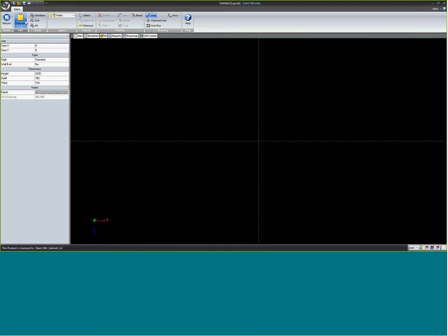Now you'll notice here all these other buttons are grayed out except the add button, and it won't let us get access to the objects until we have walls drawn. So I can either click on the button or hit the F2 button to be in the wall mode. Watch my ribbon bar at the top. When I click on the walls, my ribbon bar changed. So did my sidebar menus. Now I've got different options here.